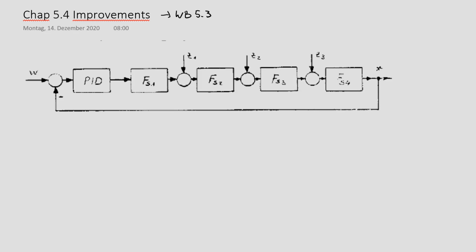And now in our example, the Z2 is too large. So the PID controller could not compensate Z2 fast enough, intensively enough, so that the user can accept the change of the difference between the desired and controlled value caused by this disturbance. So this is an example situation.